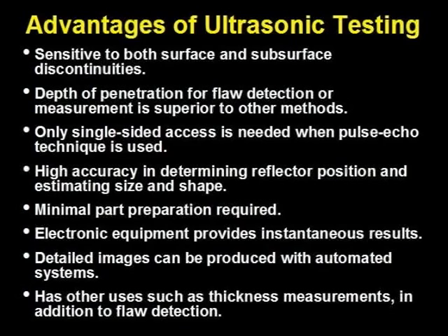The method is sensitive to both surface and subsurface discontinuities. The depth of penetration for flaw detection or measurement is superior to other methods. Only single-sided access is needed when the pulse echo technique is used. Ultrasonic testing provides high accuracy in determining reflector position and estimating size and shape. Only minimal part preparation is required.